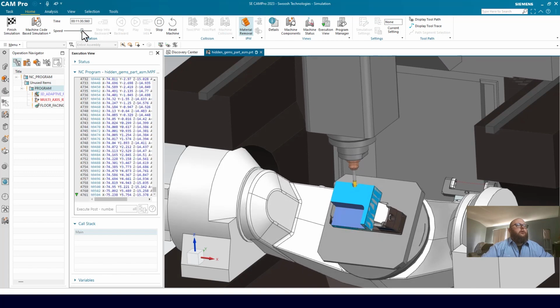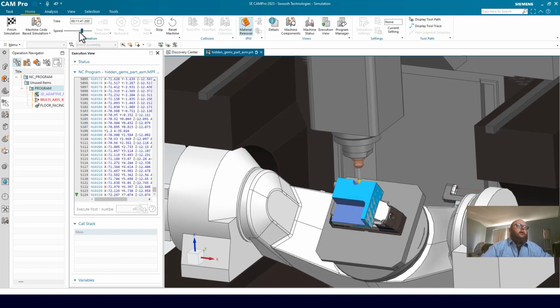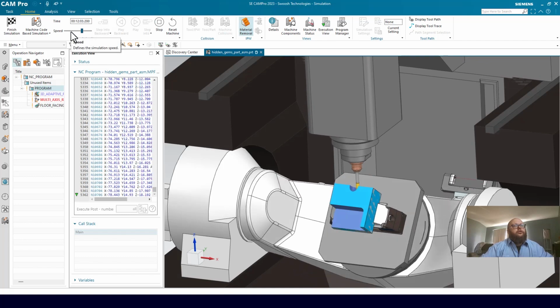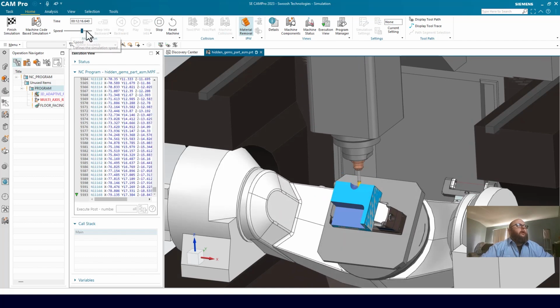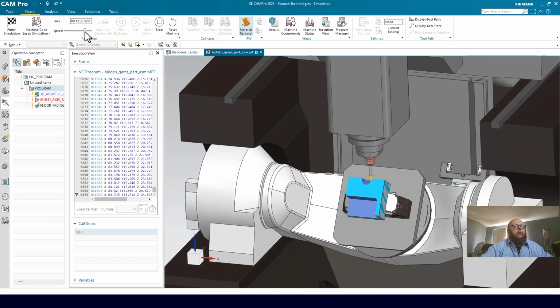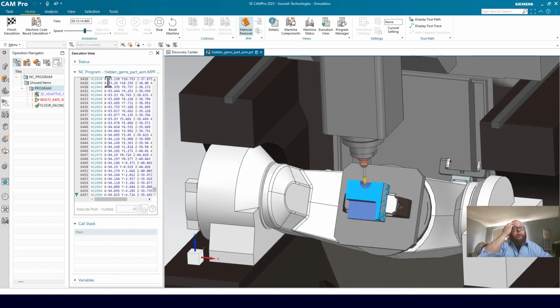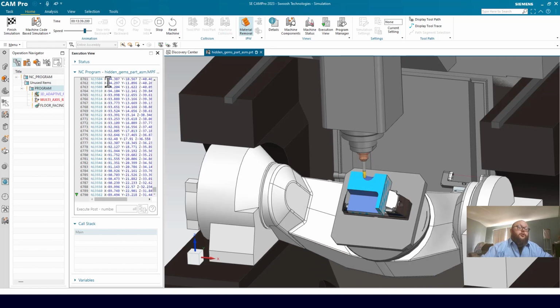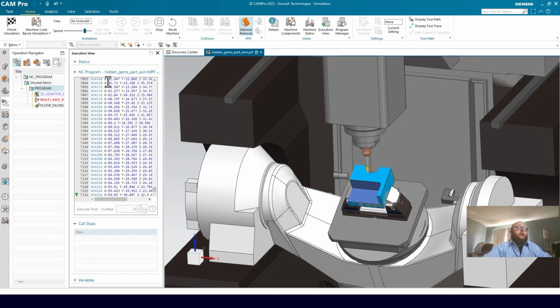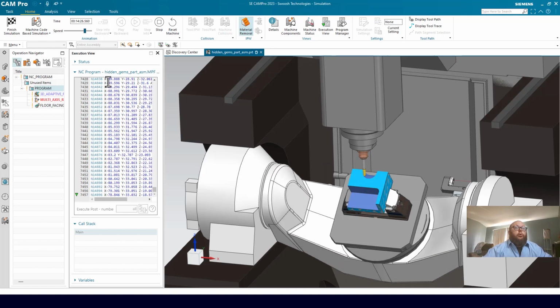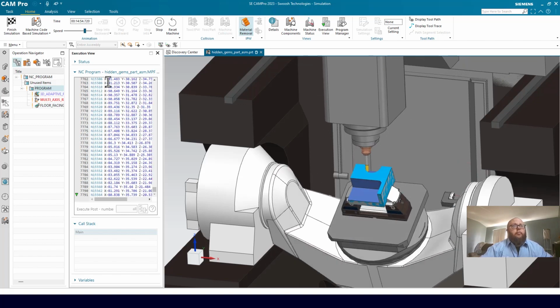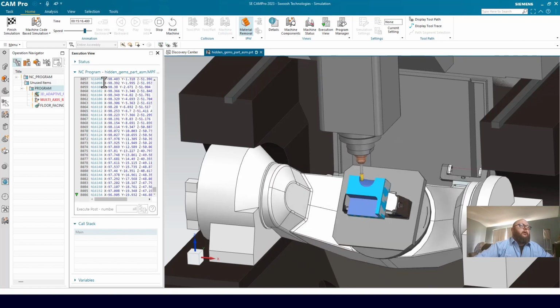You can see all those motions that you're always able to check between all your operations, the true motions your machine tool is going to be making when you drive off of the machine code. That's really important when you get into 5-axis machines and mill-turn machines with a rotary B axis. These become very crucial.